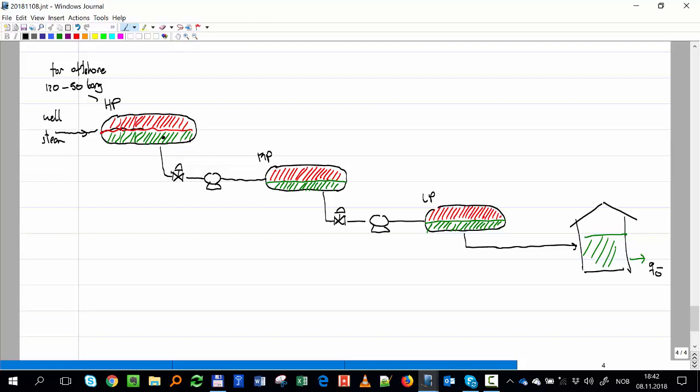Here, the fluid I'm taking is exactly at saturation, right? When I take the phase envelope of this fluid, I'm exactly here. So let's say it's an oil. If we look at the gas that comes out, on P and T, this point will be on its dew point line.